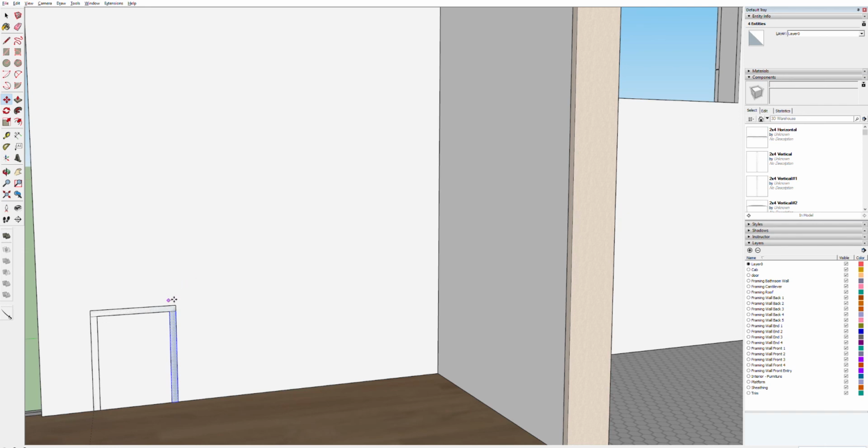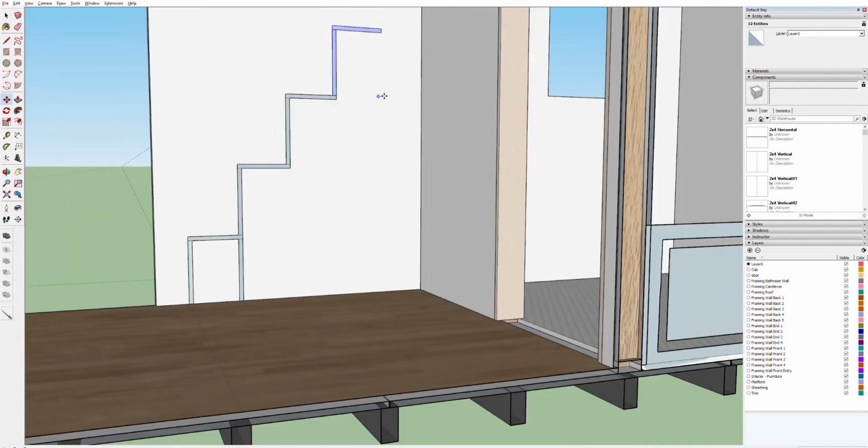Okay. Now for this, our subsequent risers are 12 1/2. Whoops. So let's rectangle tool, 12.5, comma 0.75. And let's copy this tread. Okay, so now that we got that, let's copy these. Let's see where we get.